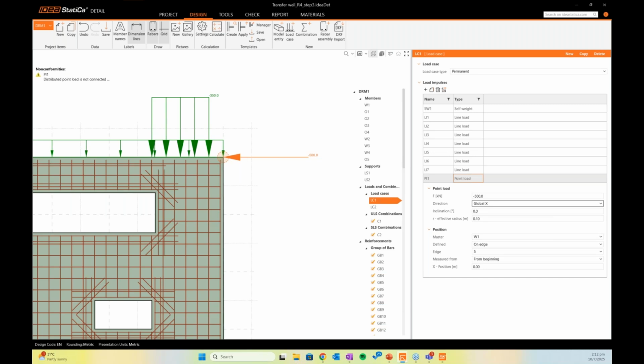How can you determine the difference between singularity and stress concentration? Yes, this is a very good question. Stress singularity usually happens in the change of geometry. So the sign would be, if you keep reducing your mesh size, meaning making your mesh smaller, and it's a stress singularity, then the stress will keep going up until it's very high. But if it's a stress concentration, if you make your mesh smaller, it will increase a bit, but it will be around the same level. So that you will know that this is a stress concentration. But if it's singularity, it will keep going up very high.